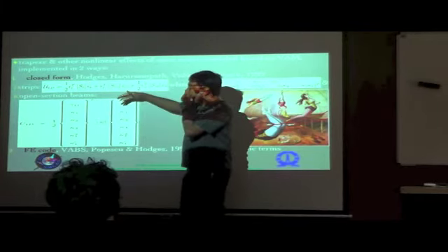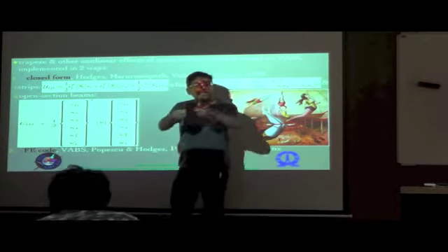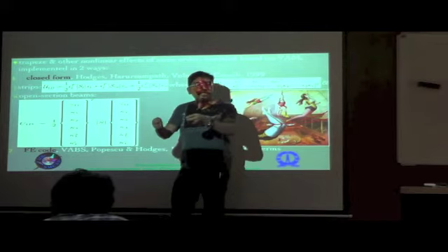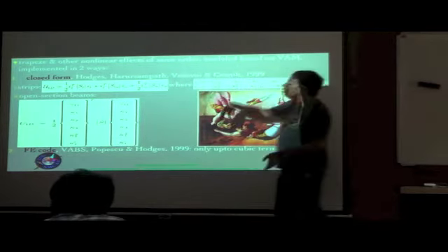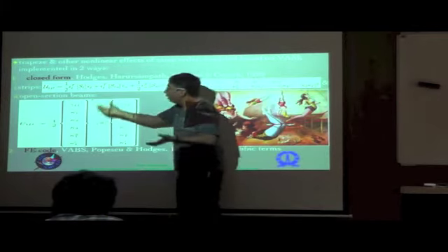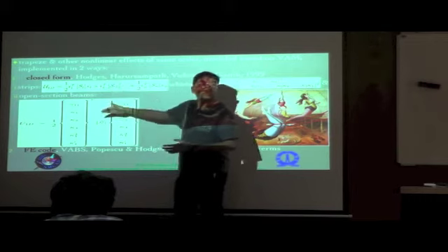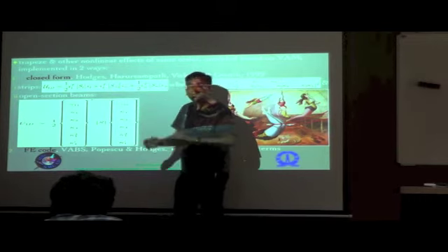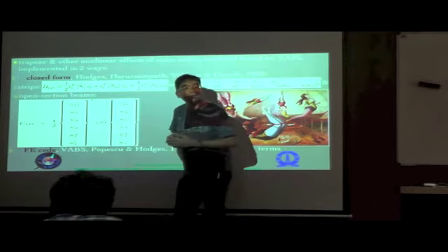So this is again something which is strange to a lot of beginners, that a strip which looks so much simpler in terms of the geometry is so much more complex in terms of the nonlinear behavior, whereas any arbitrary open cross section which is one step more complex compared to the strips in terms of the geometry is actually very simple as far as the nonlinear terms are concerned.